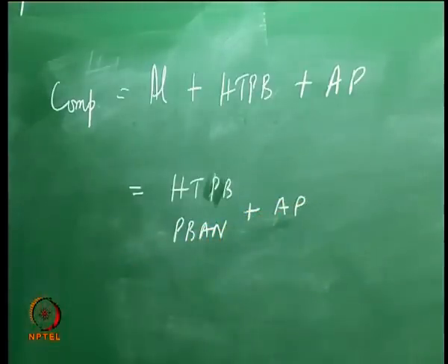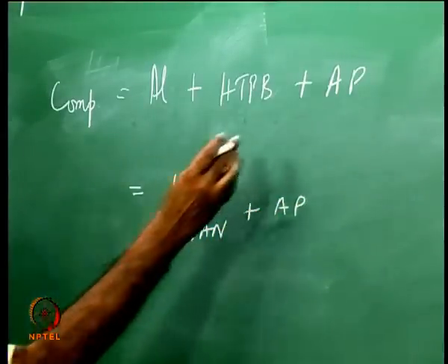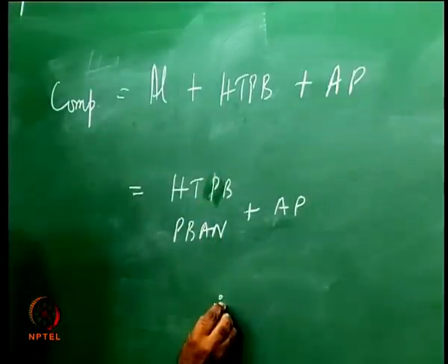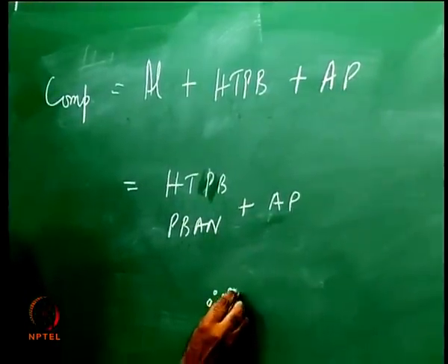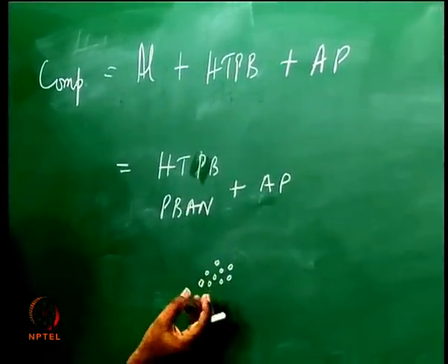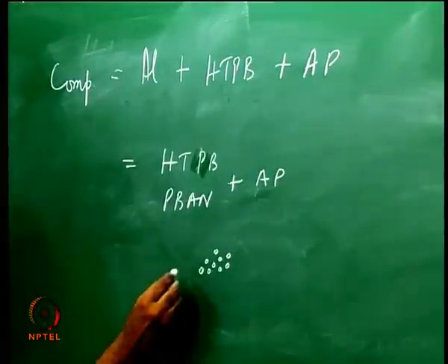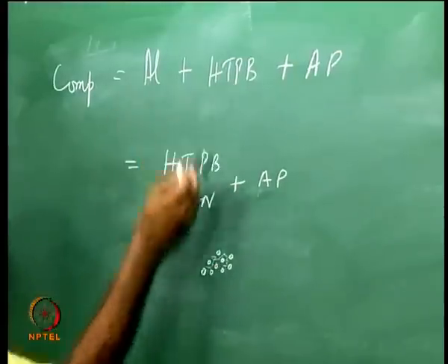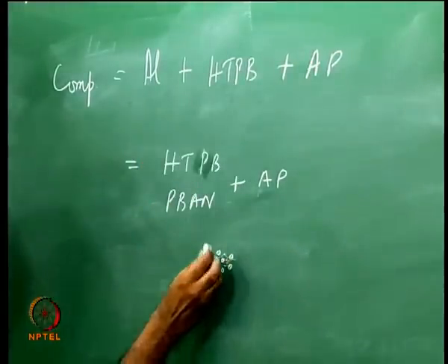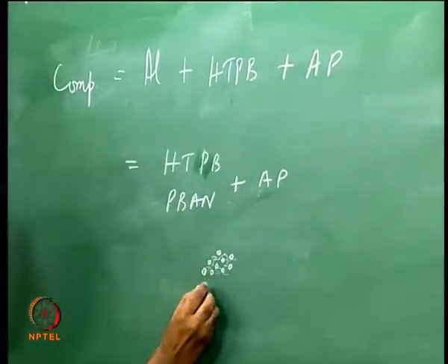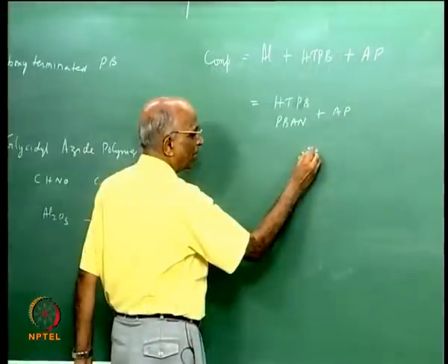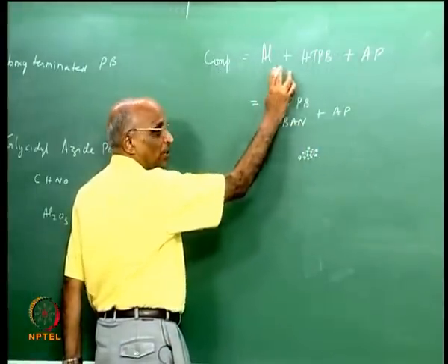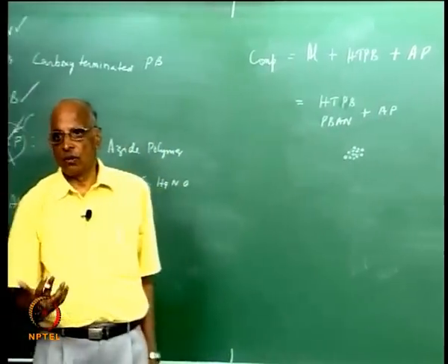These are what are called composite, because ammonium perchlorate comes as crystals, small spheres or particles, and you bond these together using the binder over here. This is a non-aluminium propellant. If I still put aluminium powder in it, well, I get this particular composite propellant. These are the composite propellants.